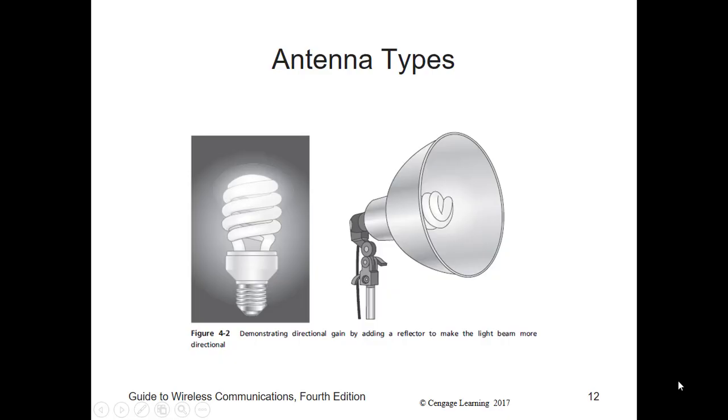Which then takes us to our active antennas. Active antennas are essentially passive antennas with built-in amplifiers. The amplifiers connect directly to the piece of metal that forms the antenna itself. Most active antennas have only one electrical connection. The RF signal and the power for the amplifier are supplied on the same conductor. It's intended to reduce the cost and make active antennas easier to install. Active antennas are not common due to their much higher costs.